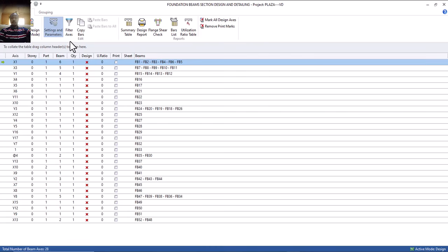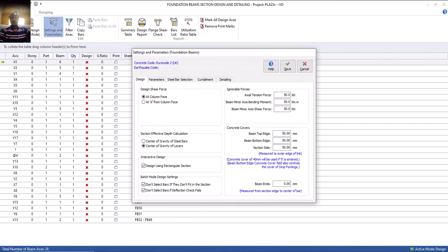So I'll click on this one now. Let's wait for it. Okay, in this place you can see that we have a design. Under the design, you can see concrete cover. For concrete cover we use 50, because it is touching the ground. Based on code, our minimum concrete cover is 50, though at times we normally use 35. But let's use 50 for all.